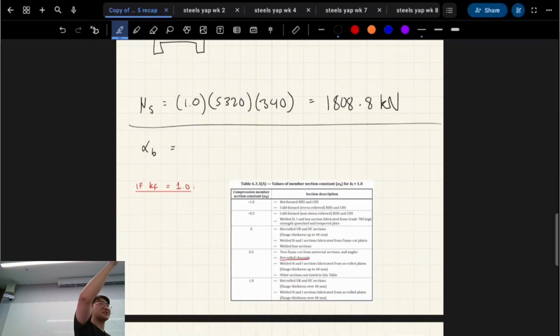I've got a little demonstration thing here, right? So here's like a piece of wood basically. But I'm going to just pretend it's a truss member that's in compression, or if it's a column or something like that in compression. So in tension, if I pull on this, the length of the actual thing has no contribution to how strong it is, right? So that's why you get cable bridges which span for like 100 meters or whatever. Cables are just purely in tension. The length of them does not reduce its strength, right?